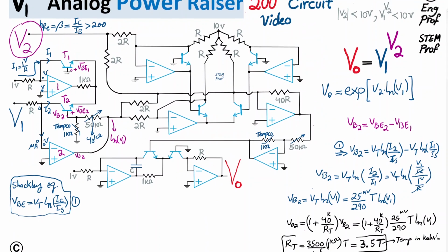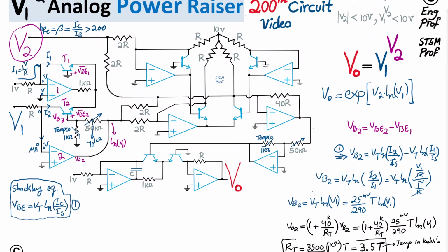For that one, it is actually more straightforward. We don't have any further VT temperature compensation, we just get rid of IS. So let's see how this is working. Again, for the value of resistors, we make the assumption they are properly selected. The good thing is, again, they are the same resistors. So if you're using, let's say, 10K or 5K, just make sure that it is a resistor with low variance, like 1% or less. My suggestion is, if possible, thin film resistors.